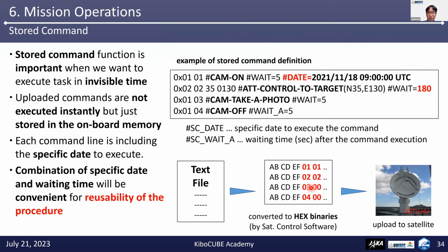Okay, actually, I don't recommend using only real-time commands. Real-time means that, yes, you push the button and execute the task. So it is a real-time operation. So I introduced the stored command function. The stored command means that the several commands are not executed in real time, and they are just stored in onboard RAM, onboard memory, and it will start after the trigger or the time.